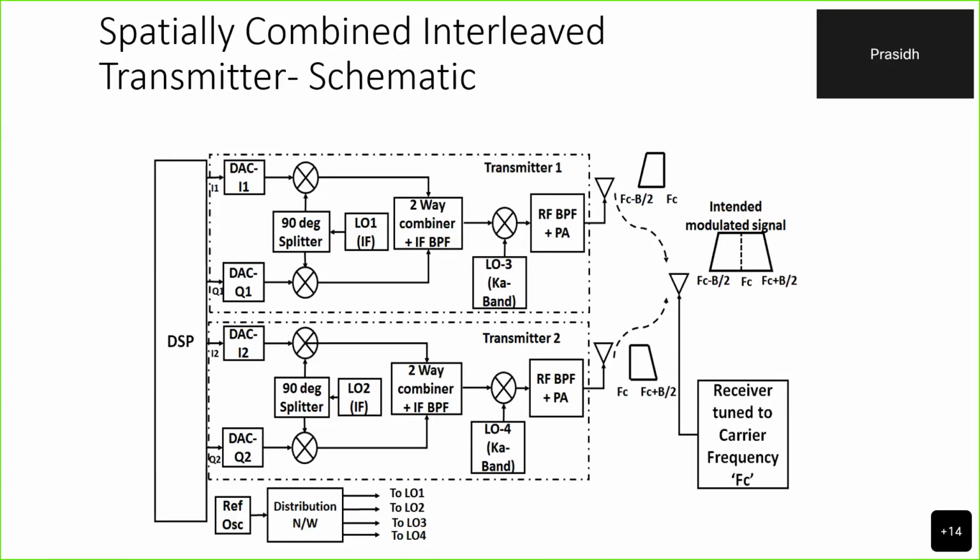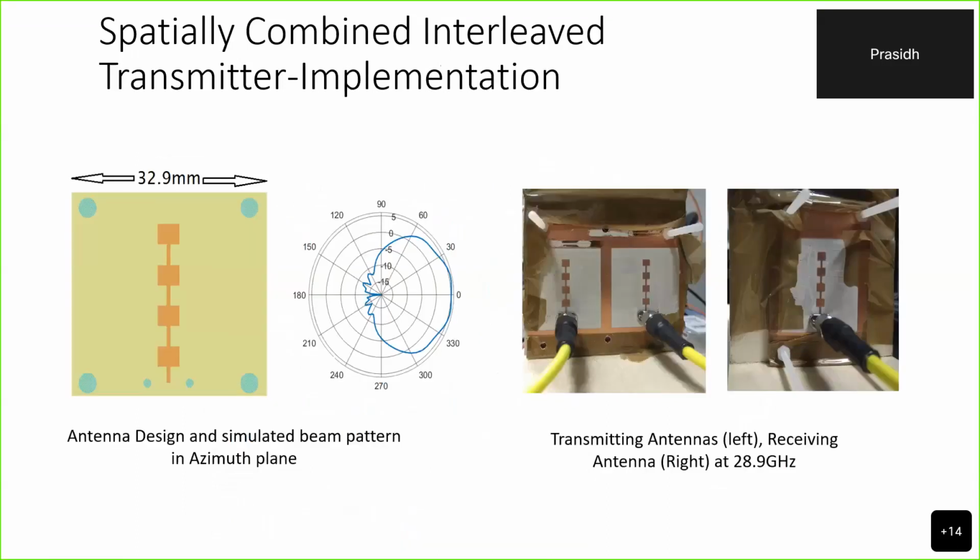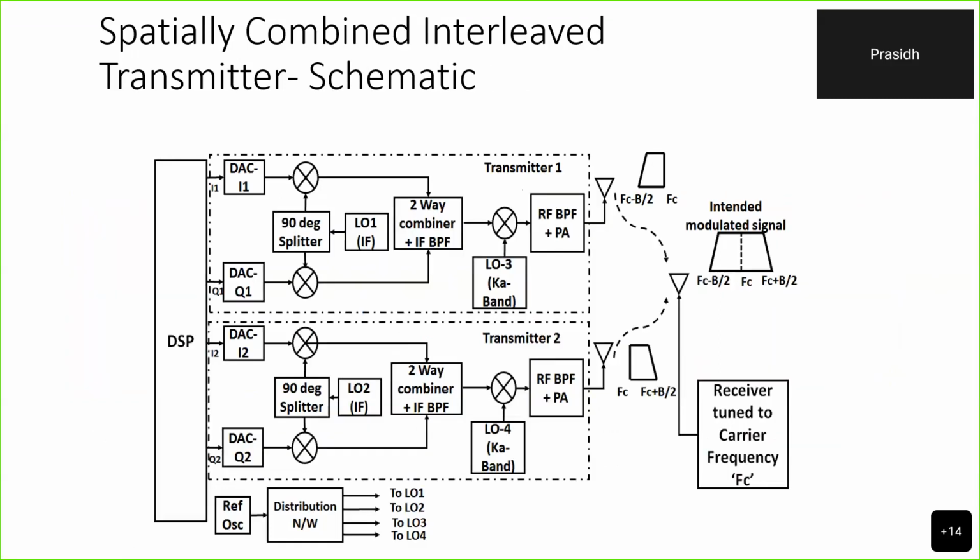Now, how about dealing with terrestrial signals like OFDM? Because in OFDM we are already modulating the subcarriers, it shouldn't be difficult to extract the subcarriers, upconvert them, amplify them individually, and then combine them spatially. But this gives a specific advantage, because if the spectrum is rectangular, the time domain signal is going to be a sinc, and the height of the sinc is proportional to the width of the rectangle.